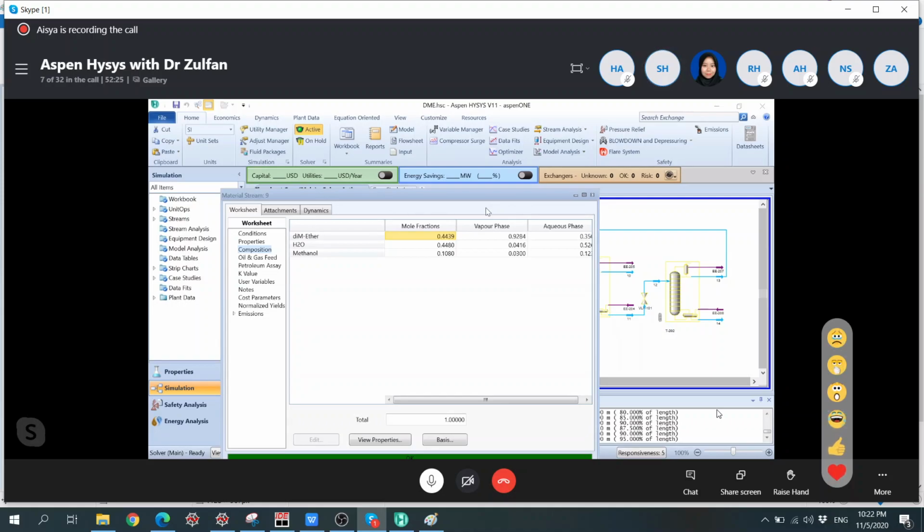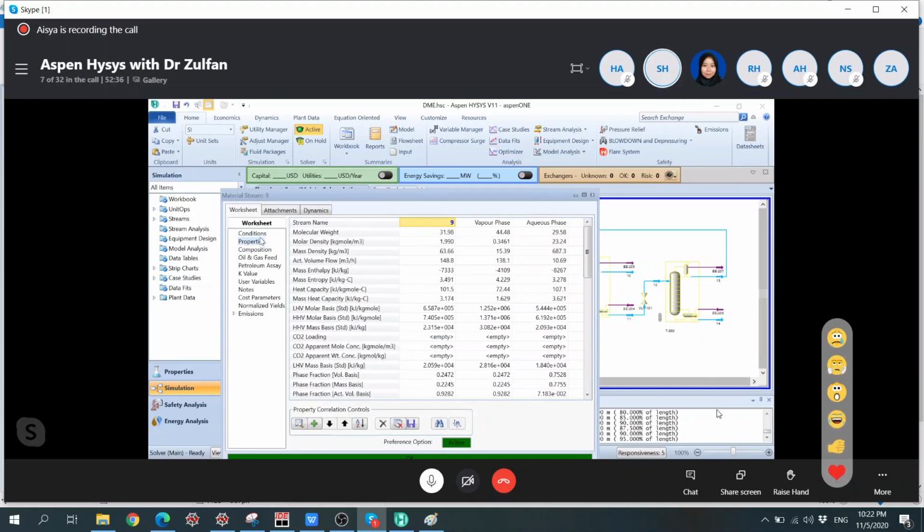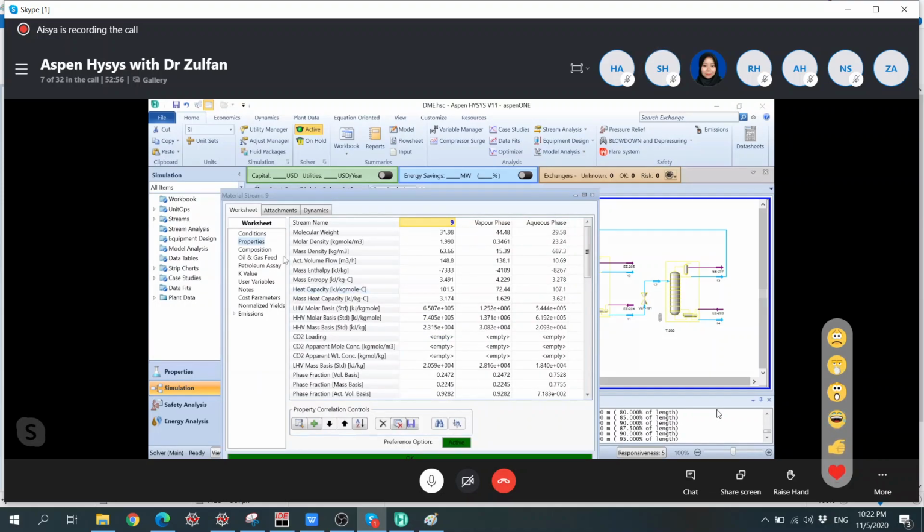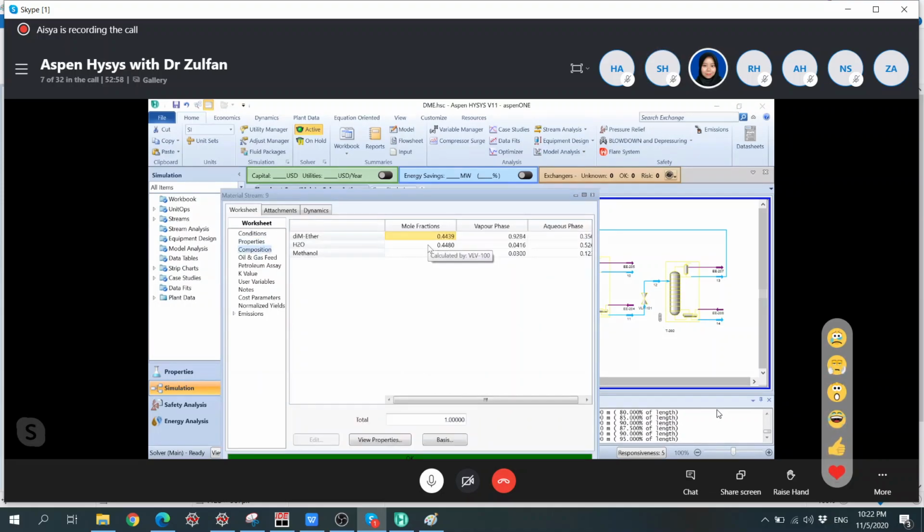Oh, sorry, this is the DME column. So it's 44% DME. How much DME is coming in, in flow rate? 296.1 multiplied by 0.4439, that is your DME flow rate coming in. So now it's up to you how much you want to recover. 130, I don't know.